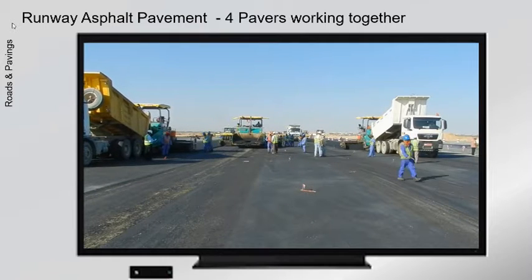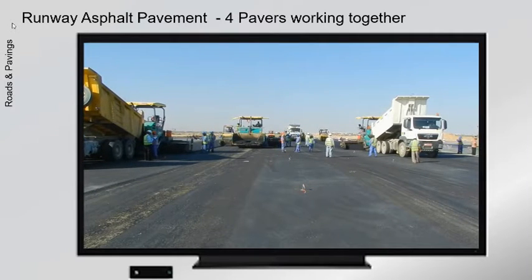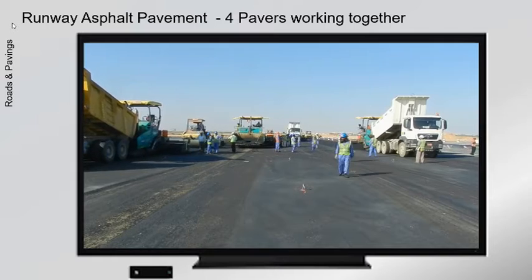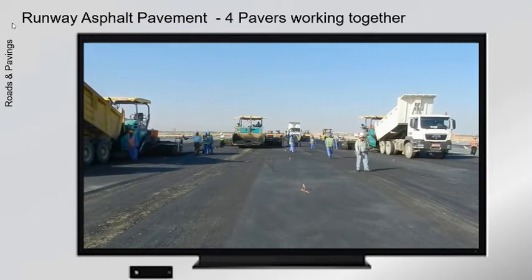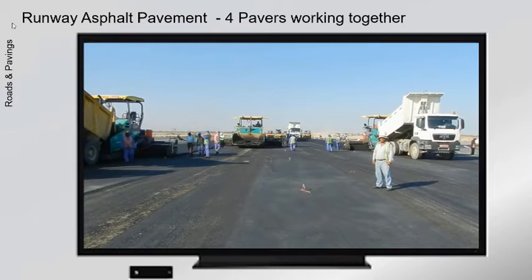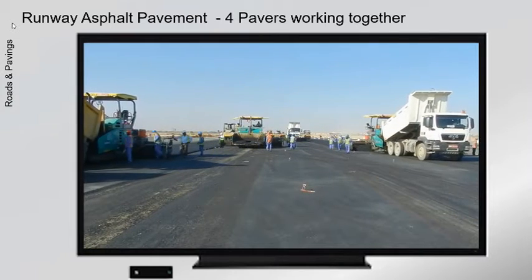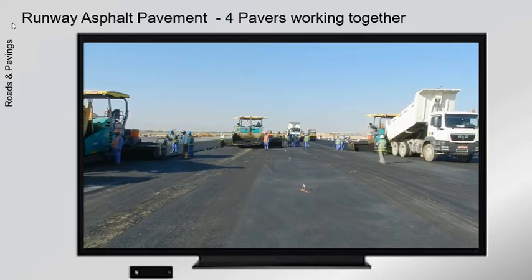The jointing and laying sequence across the runway is designed to ensure that the longitudinal joints are staggered by 300 mm between layers. Free edges that will form joints are cut back by 100 mm.